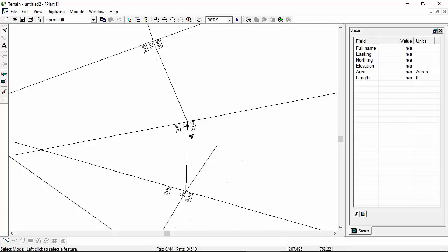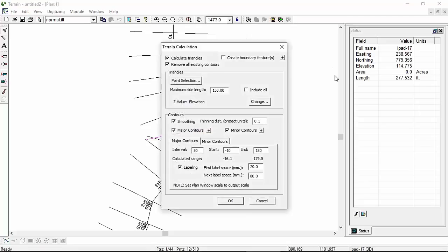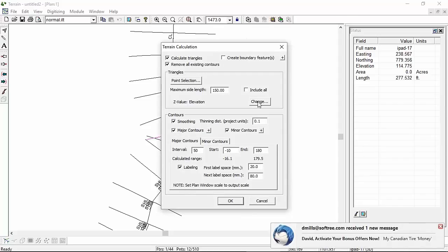They're in my terrain. Let's see what this looks like when I make a surface out of it. So each of these things has all the surveyed points in it, which contain X, Y, Z, so I can make a terrain model. Terrain is good for making surfaces, and it'll build contours while it's doing that. This is a relatively small model, so it won't take long.